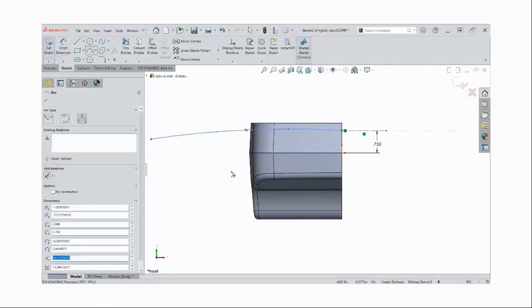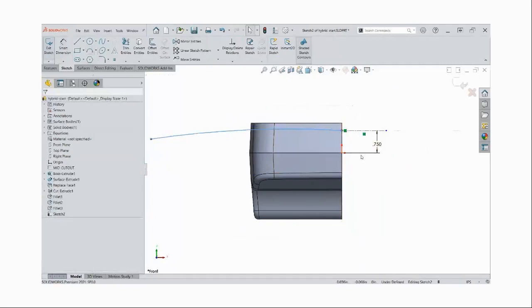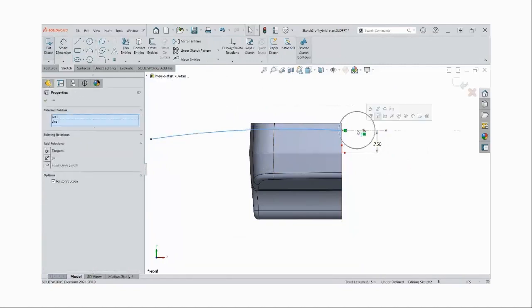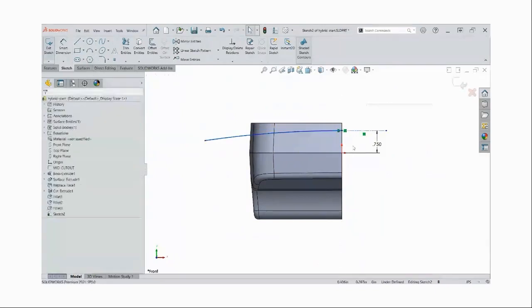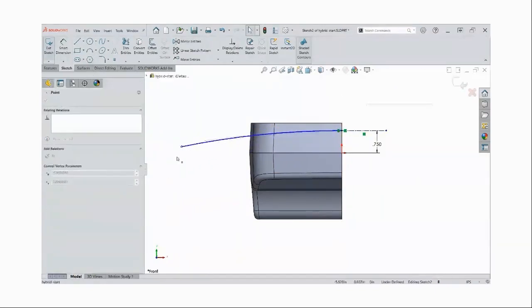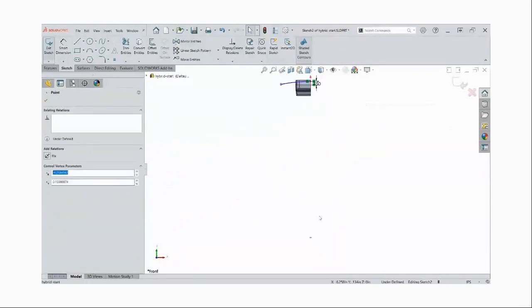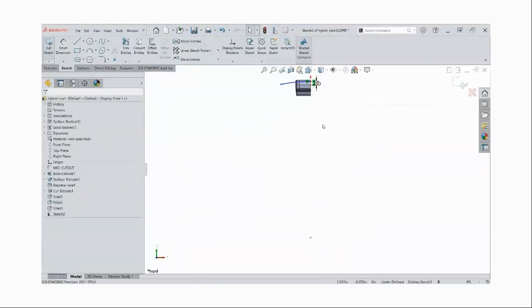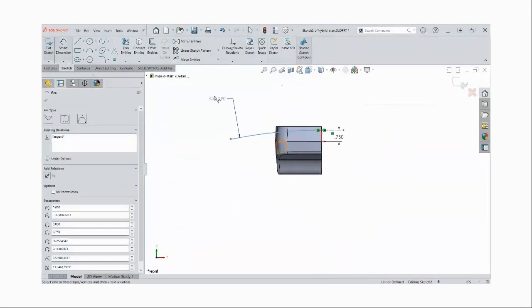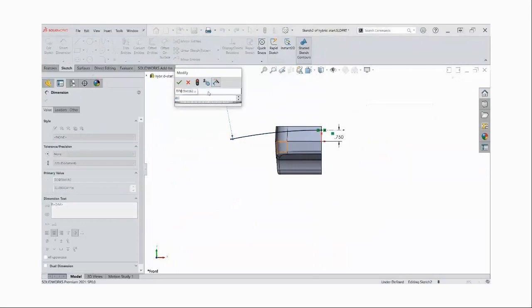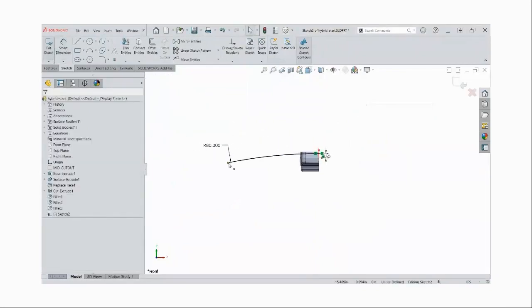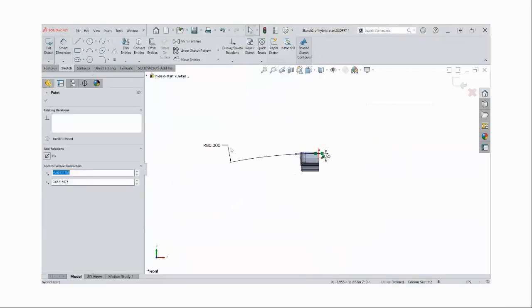And the key to getting this to mirror across correctly is going to be to make that tangent to that horizontal center line. So because the arc is tangent now, it's always going to end there. The other thing I could have done is set wherever the center point of that arc is, I could have set that vertical to the origin if I wanted to. Should be equivalent. So I'm going to give that a radius, and we'll make that really shallow, like 80 inches. The larger the radius, the more shallow it's going to appear to be.